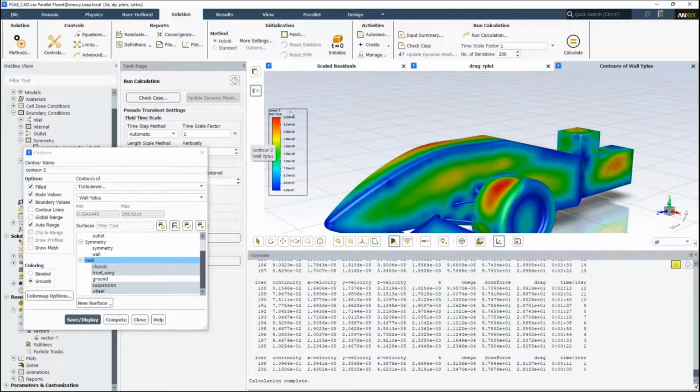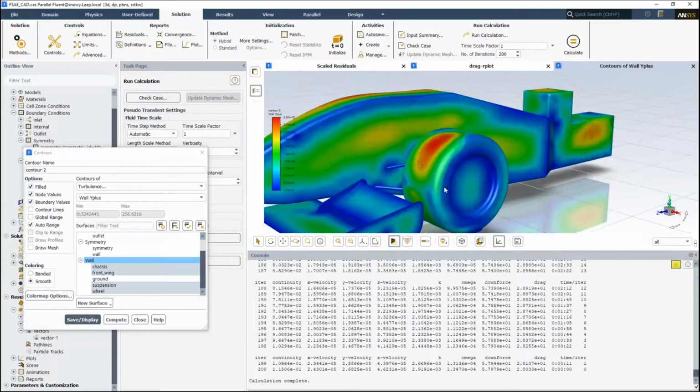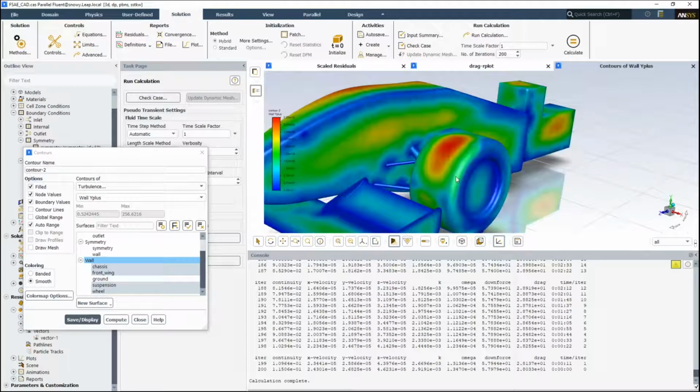If we've got a boundary layer Y1 height of 257 on this wheel, we're not going to be resolving the pressure gradients in the boundary layer accurately, which means we're not going to be picking up where the flow separates accurately. And where the flow separates and how turbulent the boundary layer is, as I mentioned before, are critical to understanding aerodynamic performance values like drag and lift.